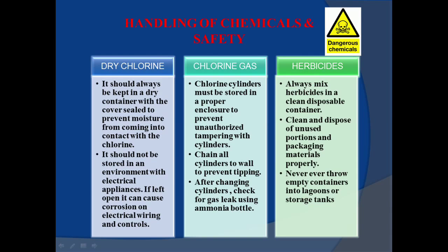Chain all cylinders to walls to prevent tipping. After changing the cylinders, check for gas leak by using ammonia bottle.